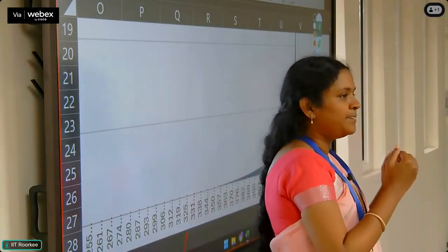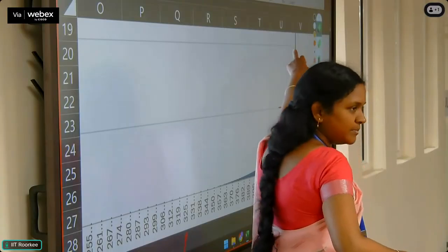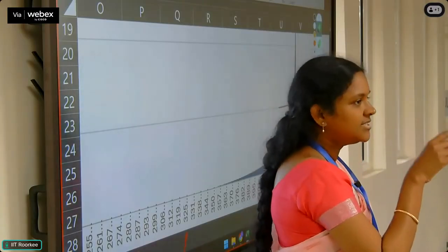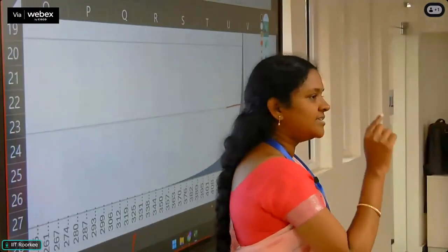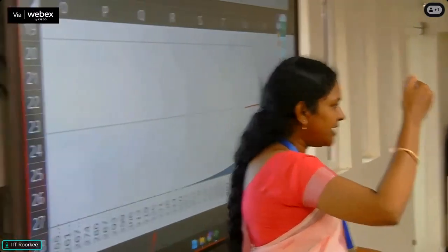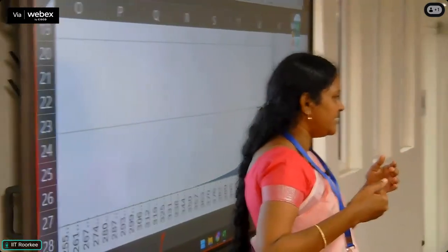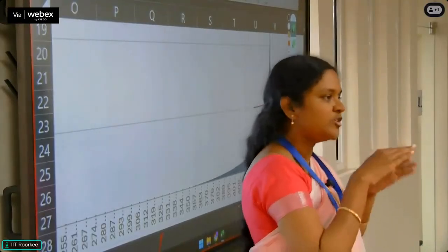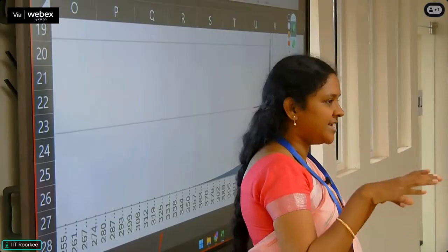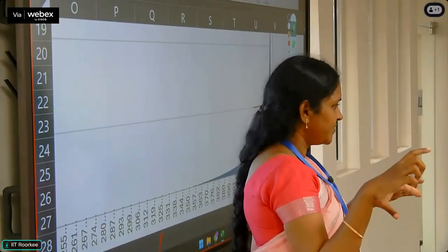So 30 mm, suppose these events are 240, means you have to subtract that 30 from that, right? So you subtract the 30, then you get the rainfall. Whatever positive values you are getting, that is the excess water which is passing, which will not be accommodated by the LID, right? So that you total it, okay?